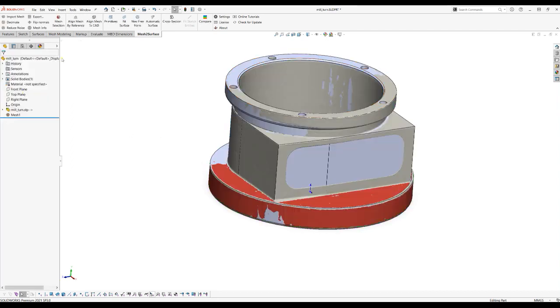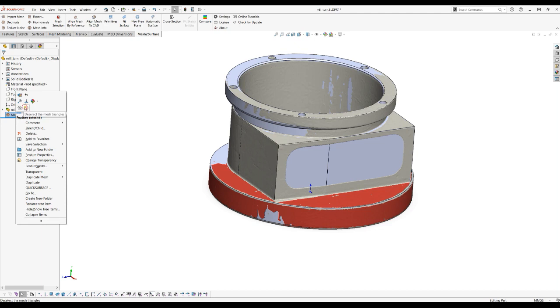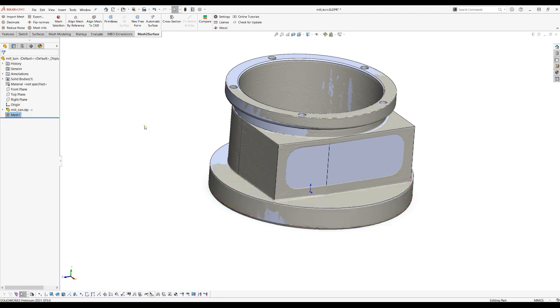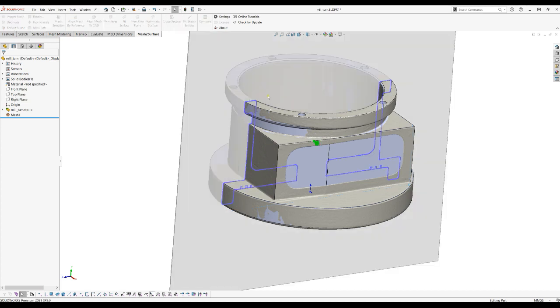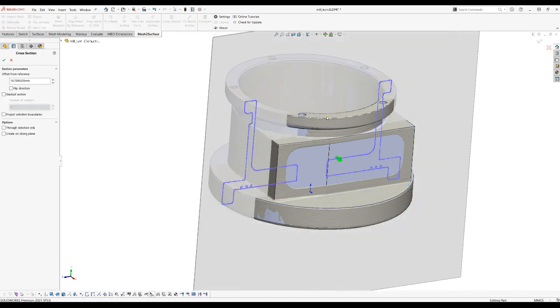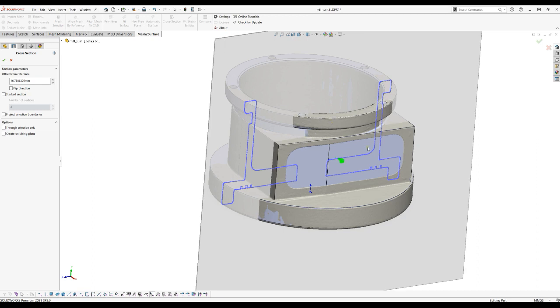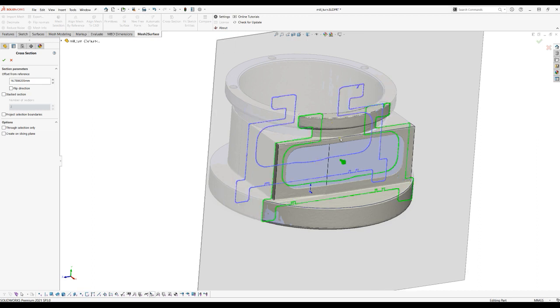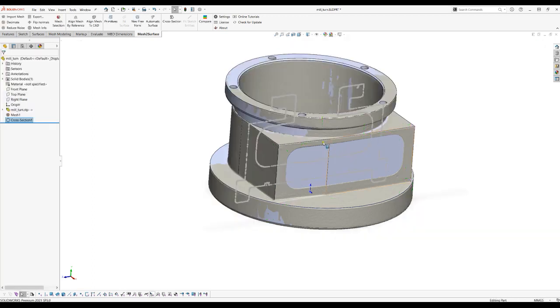So now I will just unselect everything, as we have aligned our object properly in space, and we are ready to go. Probably I can just use the right plane and we'll create a cross section very quickly, dragging so you can see the functionality here. I can just take a section of this and we'll create a cross section, and with this cross section later I can extract my sketch for the extrusion here as a cut, and we'll modify my existing object.